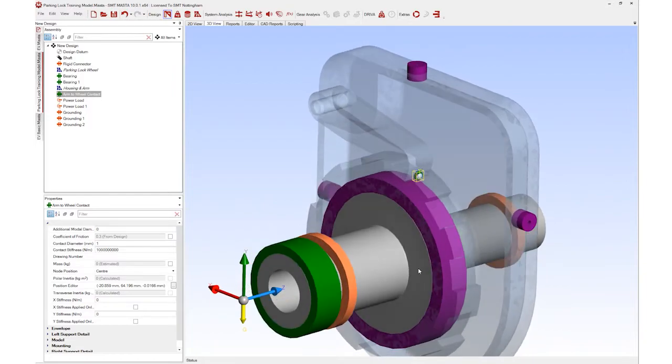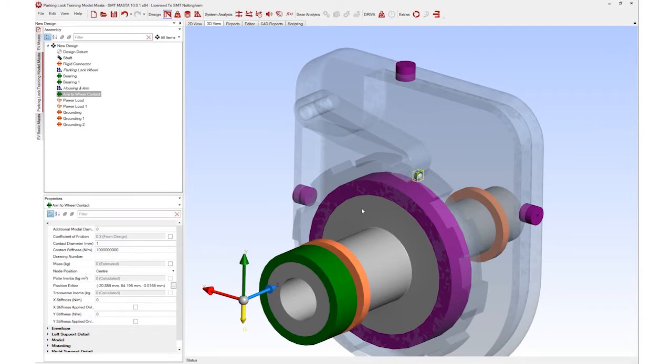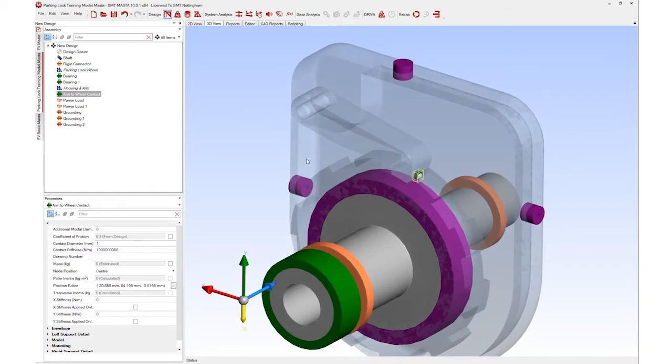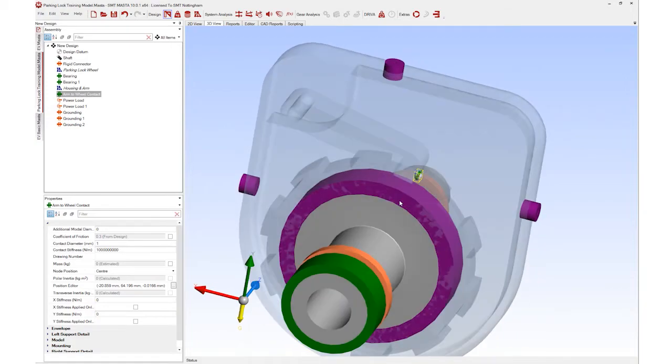So obviously, set up like this, you won't actually be able to run your model in a normal condition. This particular setup is going to ground your model. So if you try and run one of your normal load cases, it's not going to be able to do so. You'll get some failure or just not working as you expect. This would have to be an additional setup, which you'd have stored somewhere else.